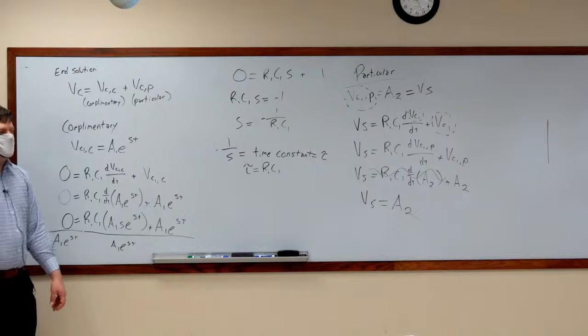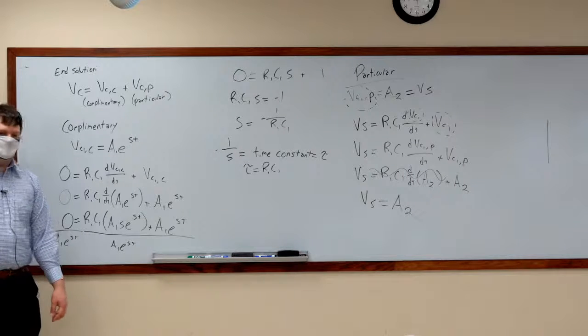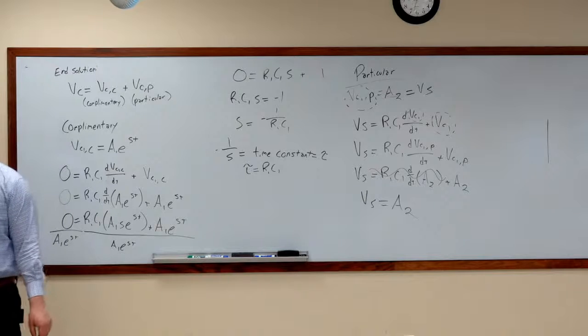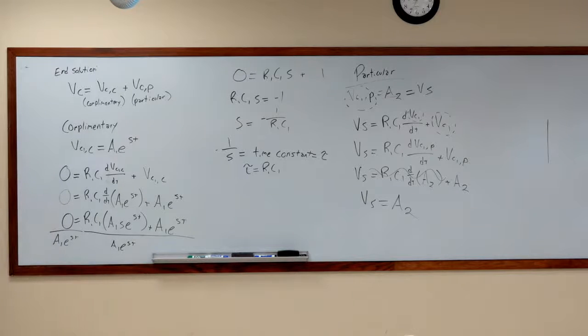And there's only one way we are going to be able to solve for it. Okay? The only way we can solve for it is something called an initial condition. We have to know at some time t what the value is of the voltage on that capacitor. At any time t, if we know that value, we plug it into the equation, and we solve it.